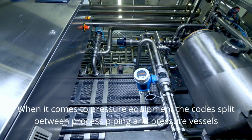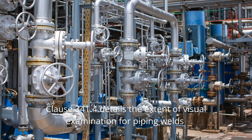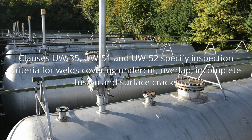When it comes to pressure equipment, the codes split between process piping and pressure vessels. For process piping, the applicable code is ASME B31.3, and Clause 341.4 details the extent of visual examination for piping welds, including those in normal and special fluid services. Acceptance criteria, including limits for undercut, overlap, cracks, and porosity, are provided in Table 341.3.2.